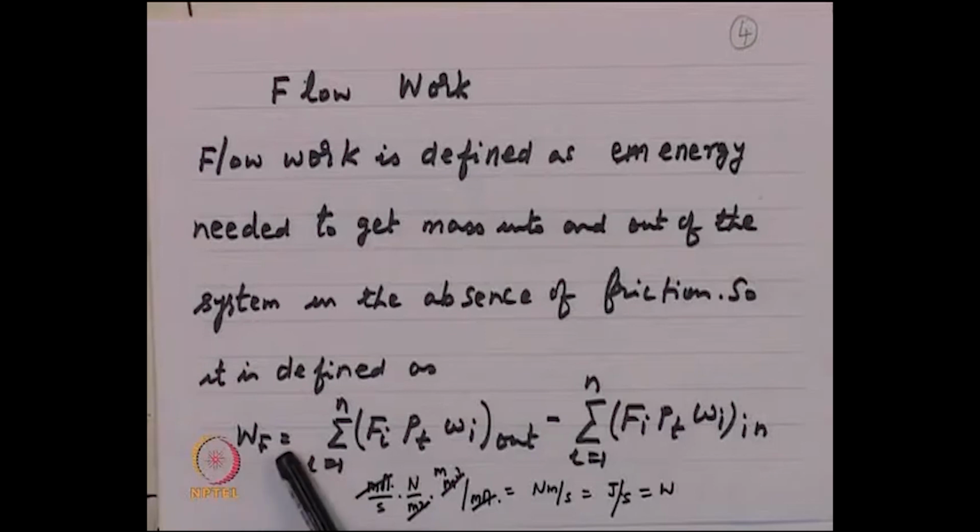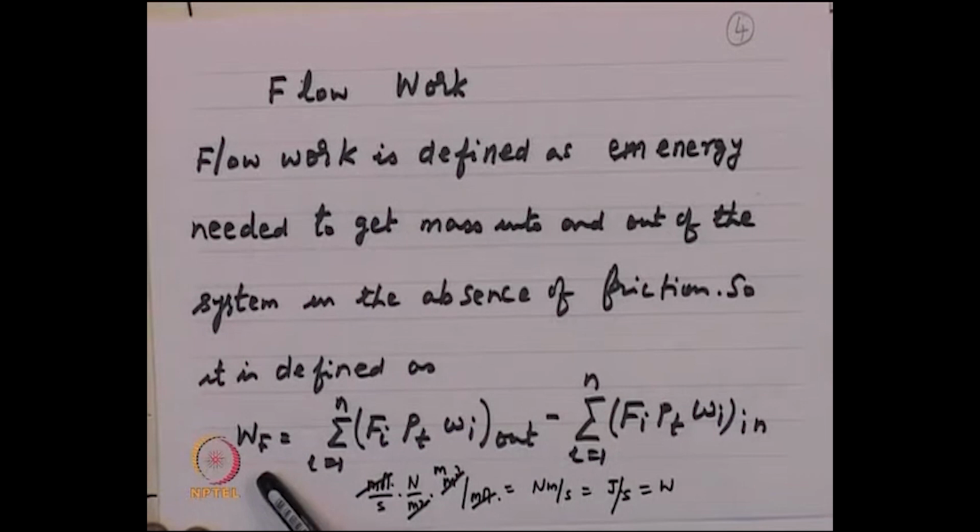So, what does that mean? Wf, which we call flow work, is the flow work into and out of a system. This difference, if it is positive, means that this particular system gives you some flow work. If this is negative, it means that you have to put in work to make this fluid enter the system and come out, even in the absence of friction.